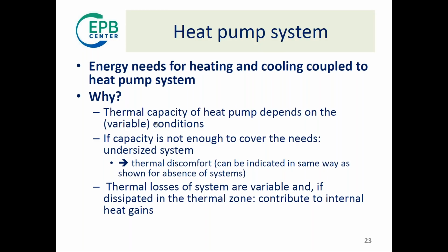The conditions vary hourly, and it has an impact. So the conditions for the calculation of the energy needs have an impact on the maximum capacity of the heat pump. And if the capacity is not enough to cover the needs, you get an undersized system, in a bit the same way as we showed in the case of the absence of the systems. You can show the discomfort.